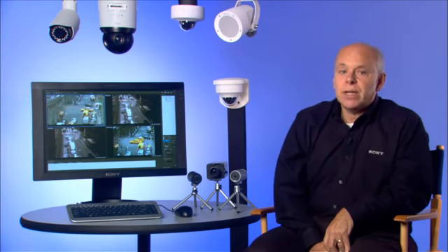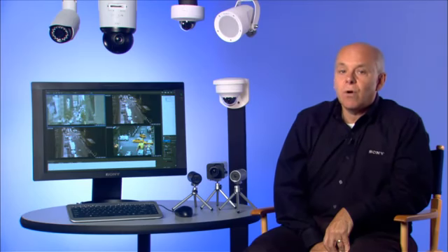These alarm outputs include a 1 amp relay contact closure, an email alert sent from the camera with a still image attachment of the event, an audio alarm, or recording onto an onboard compact flash card. 5 filters can be applied, as well as 4 video motion detection, or VMD windows.